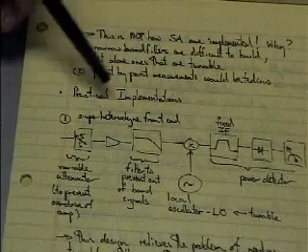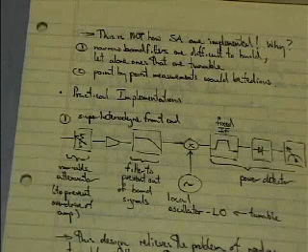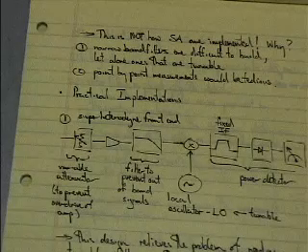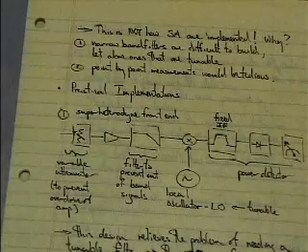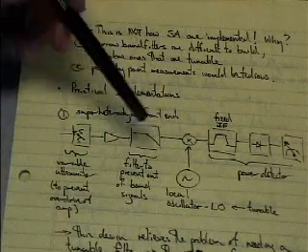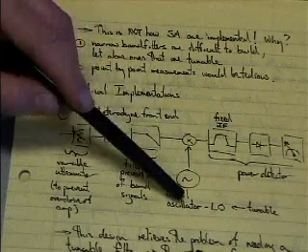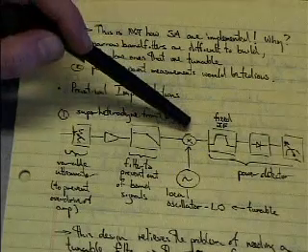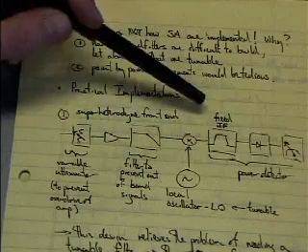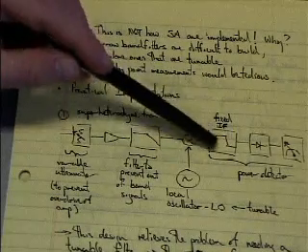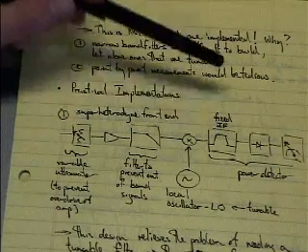Well, how does it do that? The practical implementation is to use a superheterodyne front end. This is basically the type of front end that you find in radio receivers, where you have a low-pass filter that sets up the upper range of signals that you may be interested in, and you're mixing your incoming signal with a local oscillator. The end result is that when you multiply two cosines together, you get the sum and the difference, and you set up an intermediate frequency filter to pick out the component that you want, and the other one is rejected.